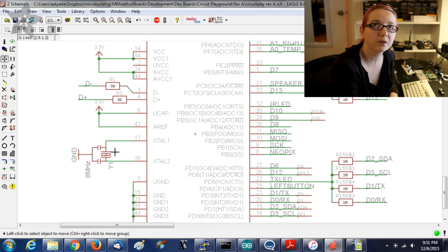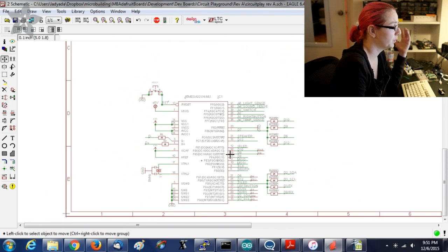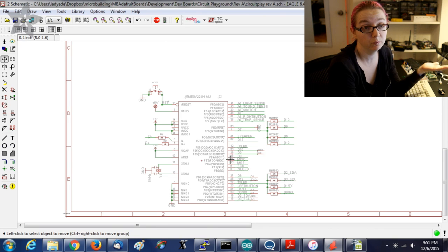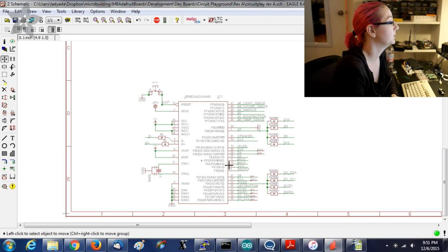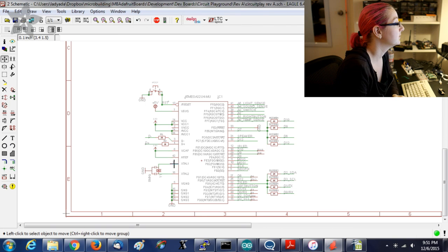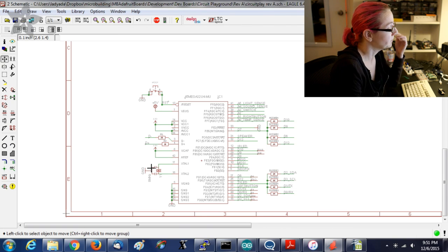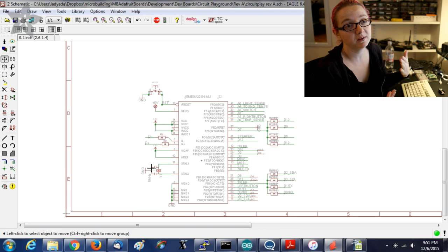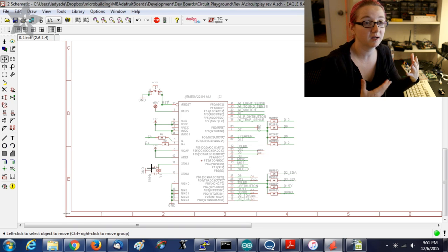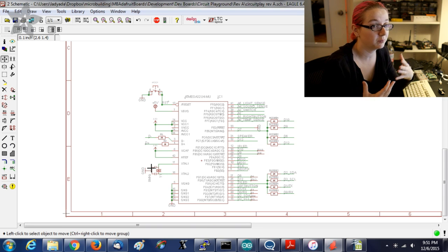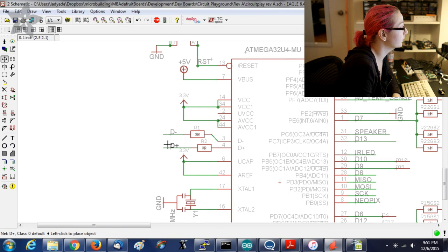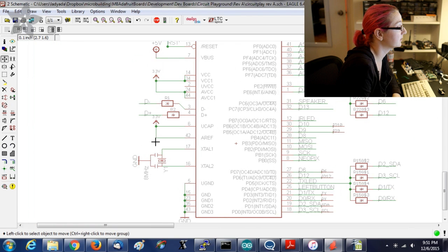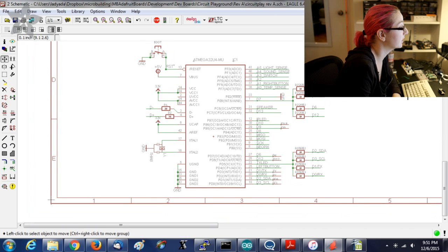I don't even know that I've ever seen a board fail under test. We do under test a full USB bootload, so we can make sure the USB interface works. I've never seen it fail due to the crystal. Again, am I designing this to go to space? No, I'm designing this to be used in classrooms where the ambient temperature is going to be 25 degrees C. So I'm cool with sticking with a ceramic oscillator. They're nice and small and cheap, and they're stocked.